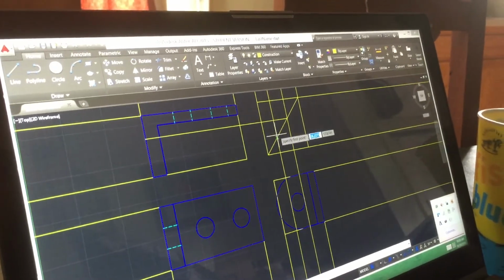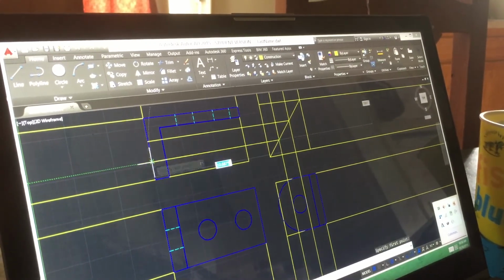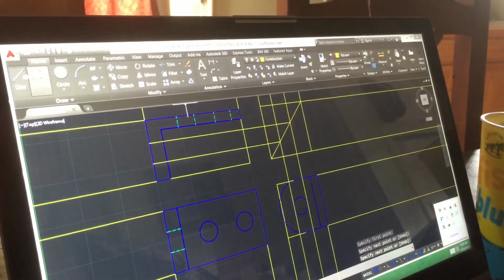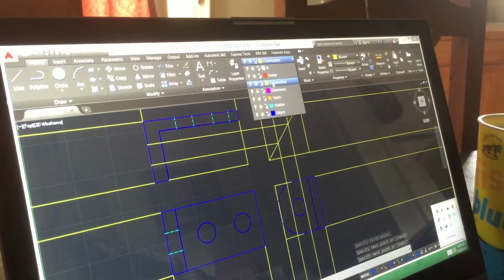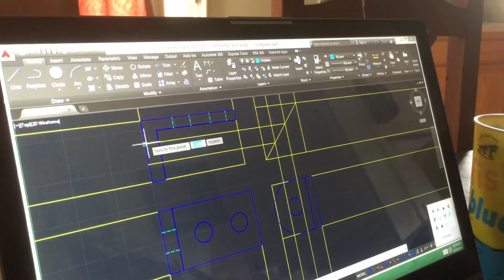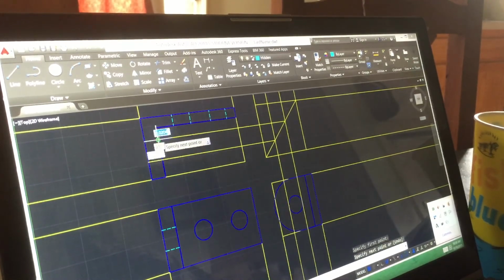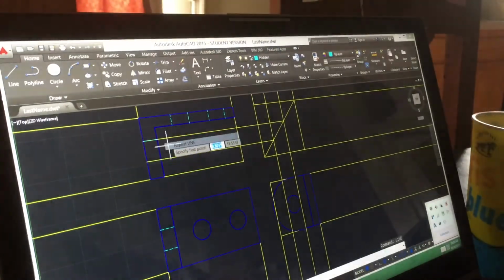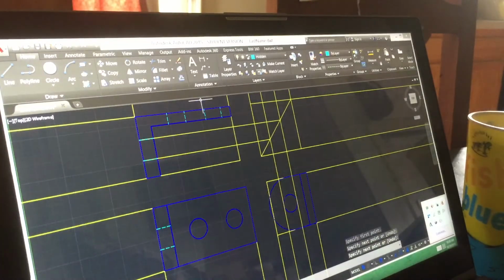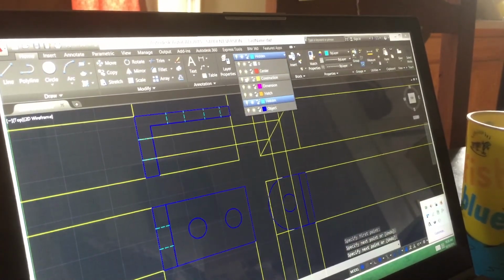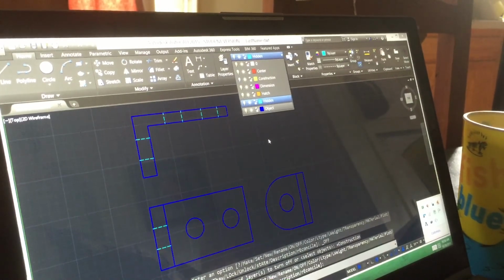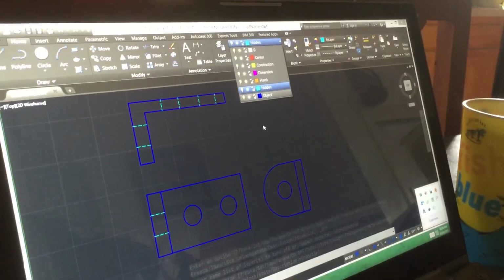You don't have to use X lines for this. You can use just regular lines. And straight over. And now I know if I use a hidden line from here to here, repeat hidden line from here to here, turn off my construction lines, and there is the three views of that object.